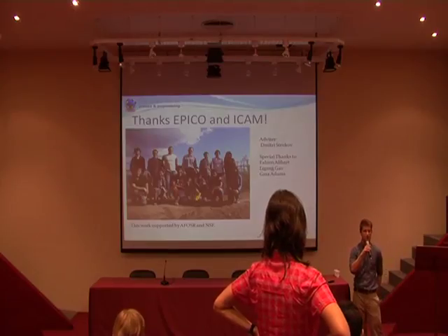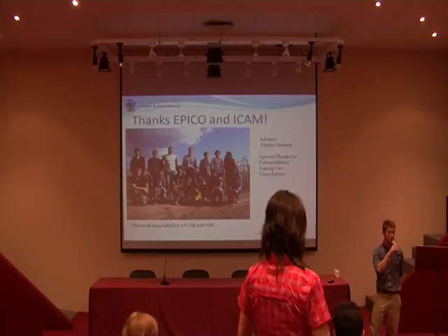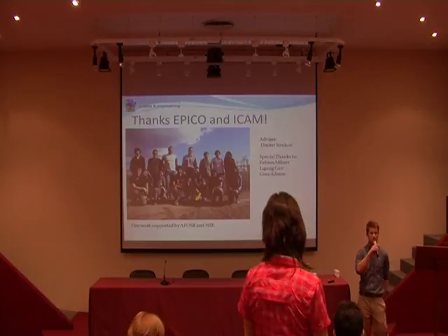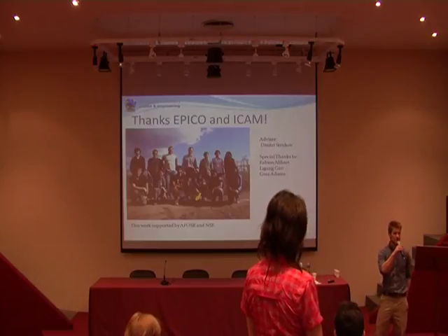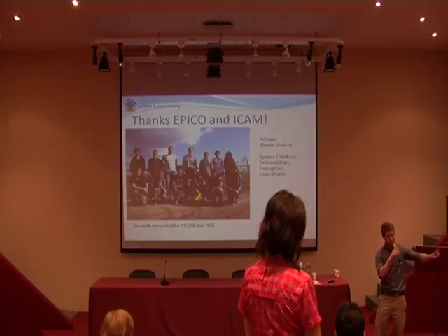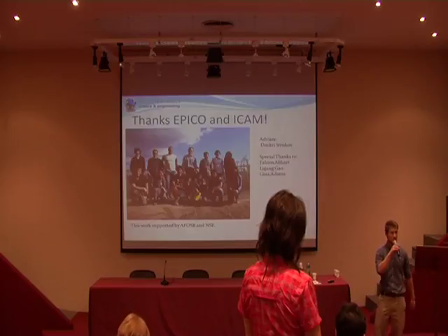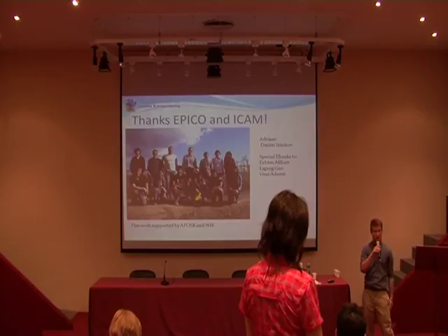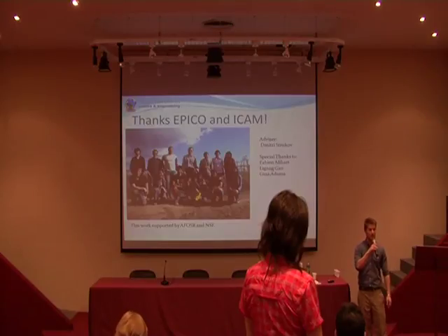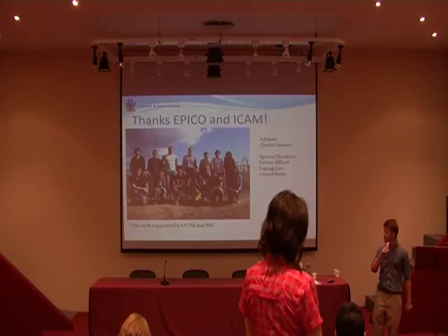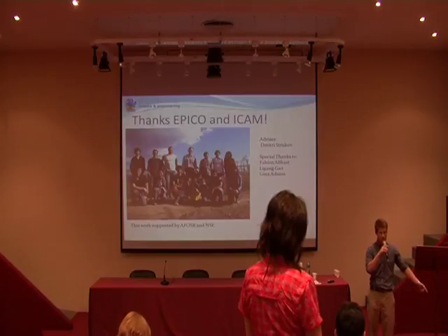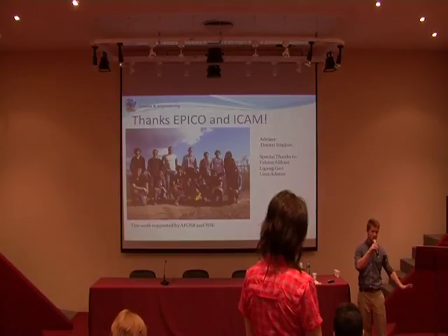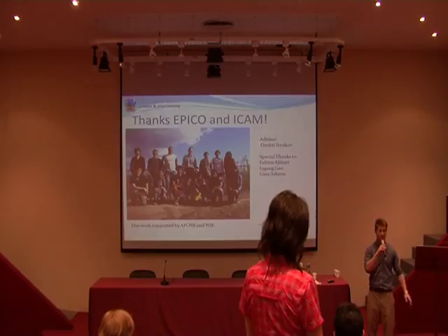But I do know that if you contact companies that do sputtering, they will actually market essentially amorphous films of titanium dioxide at more or less arbitrary stoichiometry, particularly for use as an electrode material. So I believe that, in general, the films should be completely amorphous, and whether or not that changes during the forming process, I think, is another question altogether. But I don't have any measurements to claim otherwise.